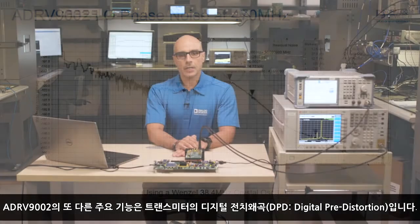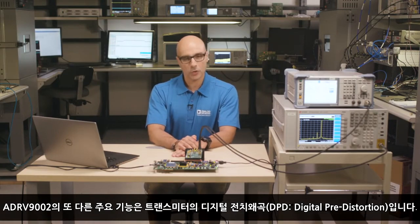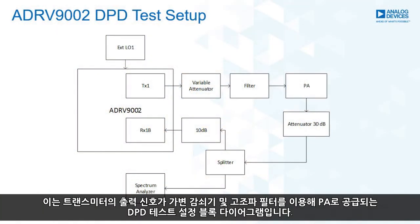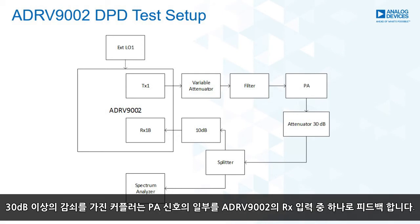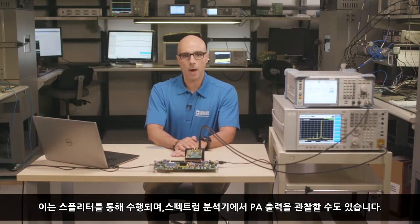Another key feature on the Adrv9002 is the transmitter digital pre-distortion, or DPD. This is a block diagram of a DPD test setup where the transmitter output signal is fed to a PA using a variable attenuator and a harmonic filter. A coupler with 30 dB attenuation feeds back a portion of the PA signal to one of the RX inputs on the Adrv9002. This is done through a splitter, where we can also observe the PA output on a spectrum analyzer.